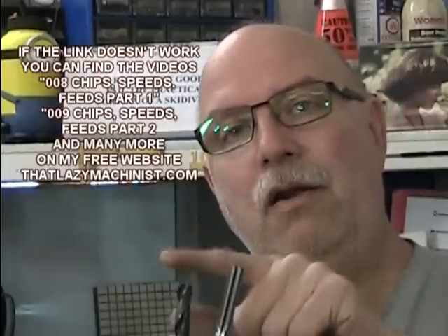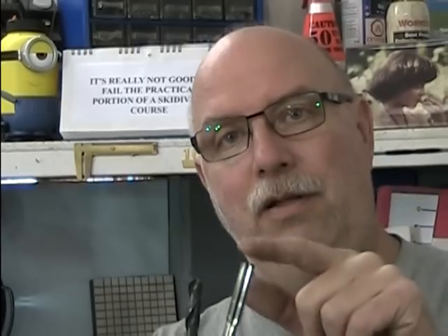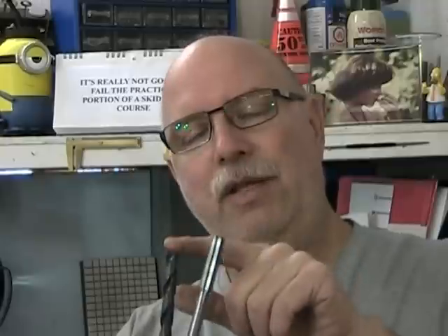So if my feed here was 3 thousandths of an inch per rev, and I have 3 times the number of cutting lips on this reamer, well, I'm going to be 3 times the feed to maintain the same cutting tooth or chip load. Sorry about that. So chip load, great stuff. So if I'm feeding at 3 thousandths of an inch here, I'm going to want to feed at 9 thousandths of an inch per rev with my reamer. So feed is quite different.